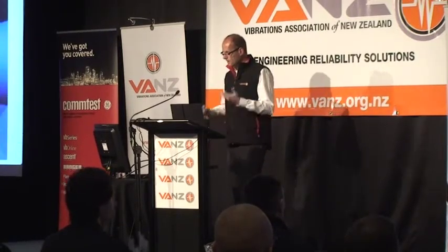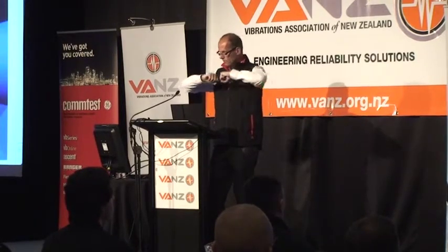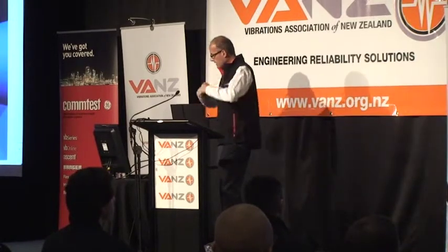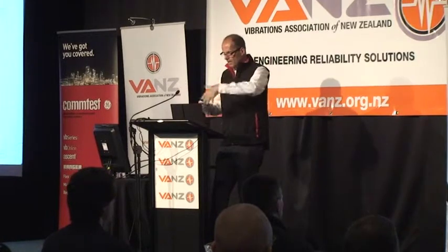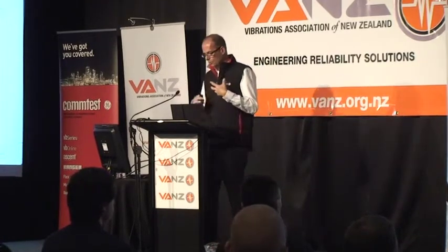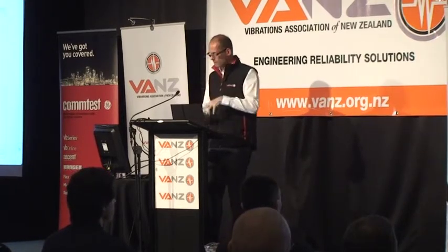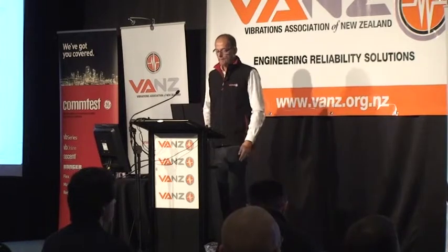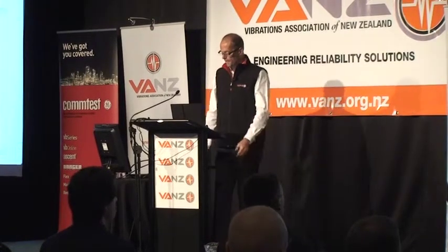Angular misalignment is different, and you're probably going to have both, but now it's more of an axial vibration. It's going to want to move axially. If we closed up that coupling, it's pulling like this. And without going into all the details, with misalignment, we can detect it through the spectrum. It's more complicated than what I'm showing here, but we can detect it. We can tell what's going on, we therefore know what we have to fix.